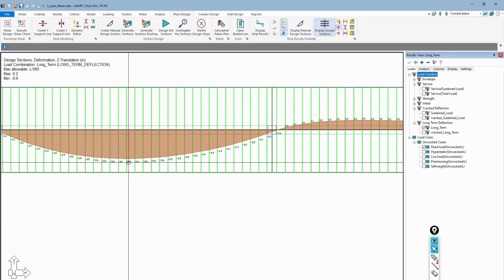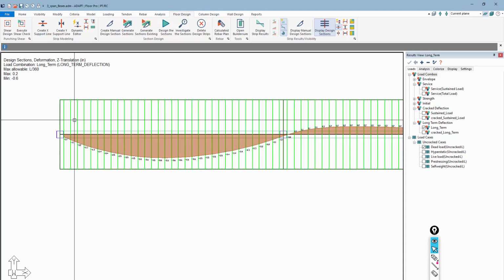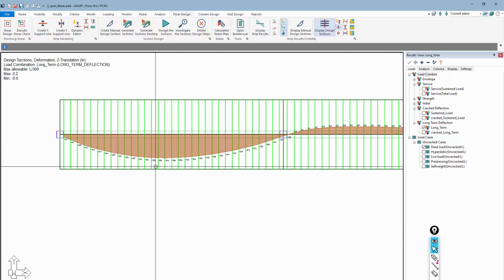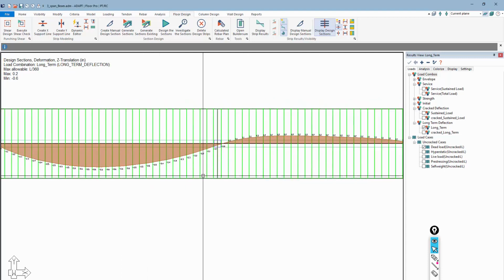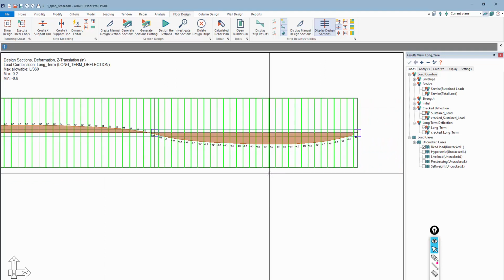So the program integrates over the shells for the basic load cases and combination solution. The crack solution is a post-process that is not really stored in the data that's being used to actually integrate to produce this result. So the long-term uncracked deflection here is 0.6 downward, 0.2 upward, 0.3 downward.